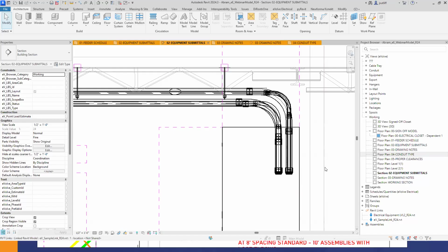if you don't get the submittals is, like you said, reference a prior project. And if the manufacturer is the same and you've got a submittal that has all of the sizes of the various amperage of equipment, then you can at least utilize that as your worst case scenario.